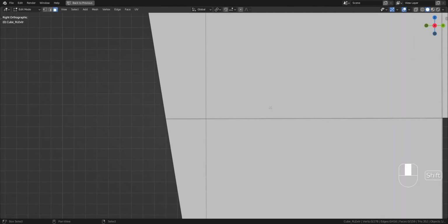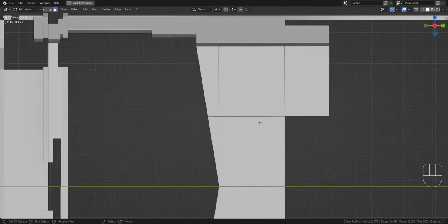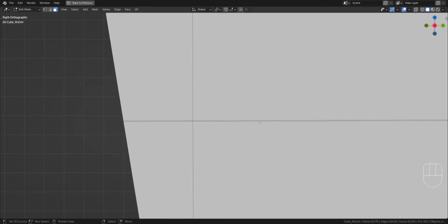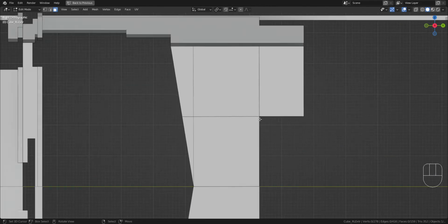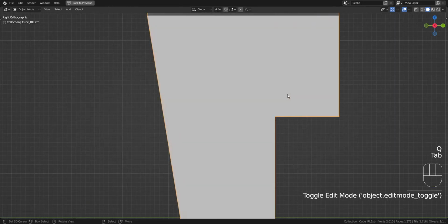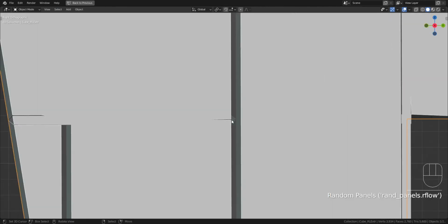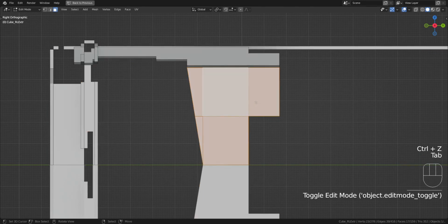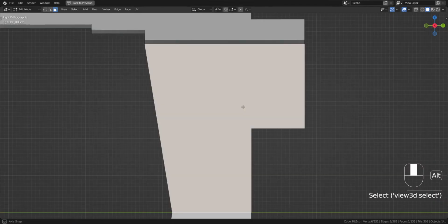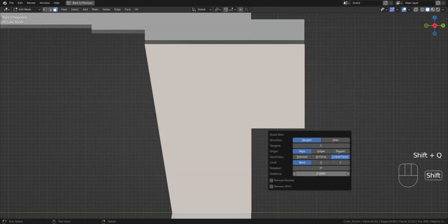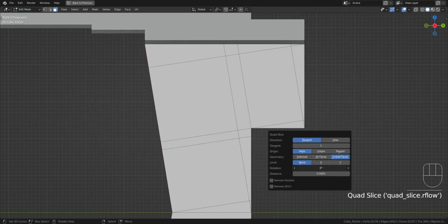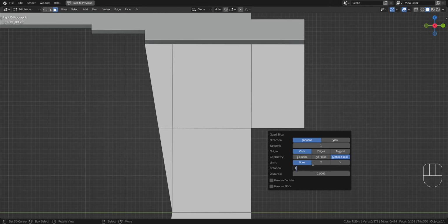Here you can see that this may look like a single edge, but there are actually two edges, and they're bad for subdivision. So what we need to do is mix it with distance. The magical distance property, linked faces, rotate. Let's do 10 degrees. Oops, not 10 degrees, too much.